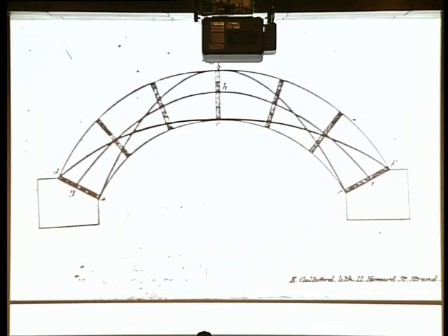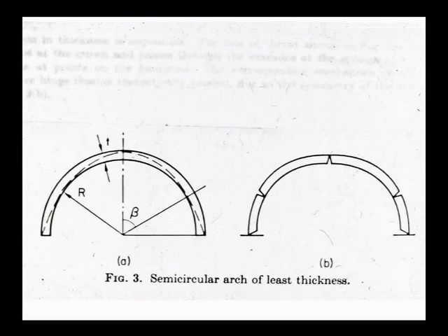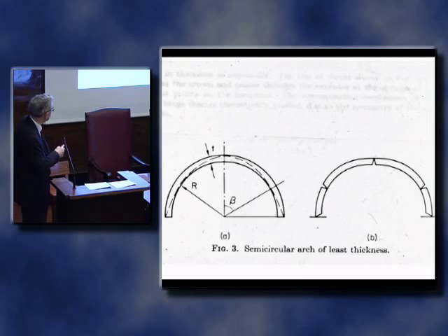This was a picture of about 1840 in England at the Institution of Civil Engineers, somebody demonstrating how arches worked. And there are three possibilities sketched there. There's an infinite number in between all of these, and these were demonstrated by the lecturer at the time. As the arch becomes thinner, of course, it is not possible to accommodate any shape, and this, in fact, sketches the minimum thickness of arch, which will only just accommodate the forces like that.